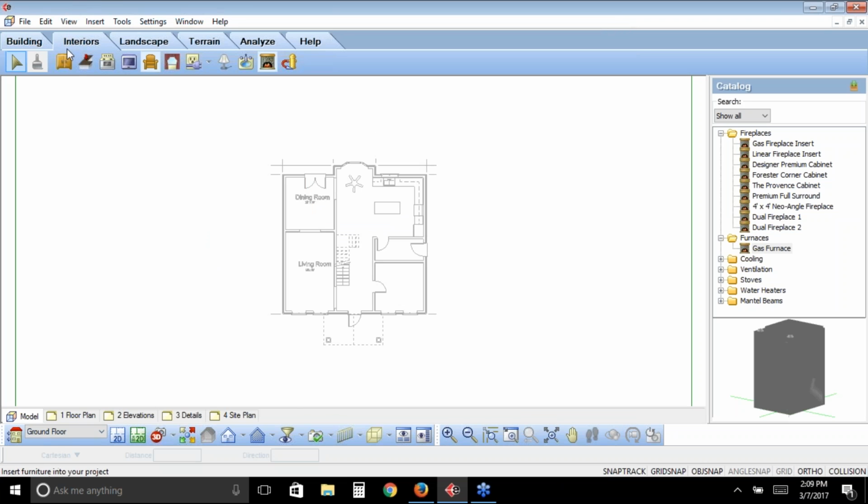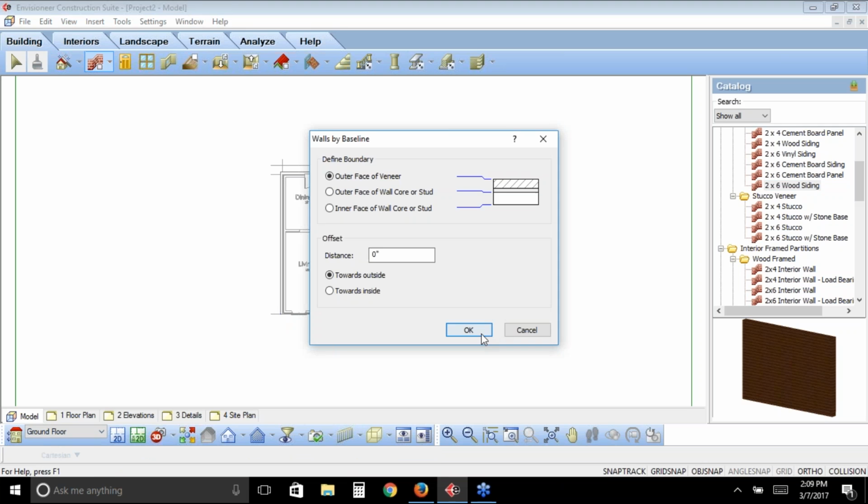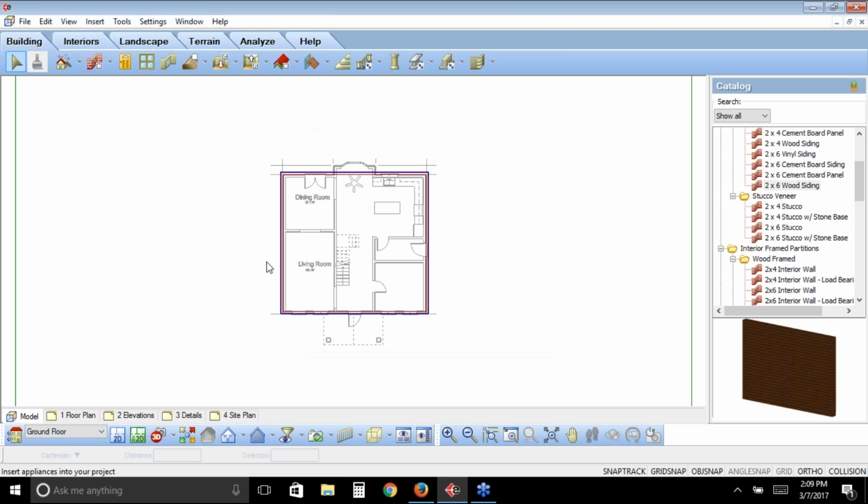And basically, you'd want to do that so that you could quickly trace over top of something, usually predominantly used for estimating purposes. Someone else has done your plan work. Now you have to do an estimate for it. So I'm just going to quickly grab some walls here, and I'll just quickly trace over top of it, and you can see how it's trying to snap to those corners for me, and I'll just pick to my original start point and say that I traced around the edges, and there's the walls around the four sides there.